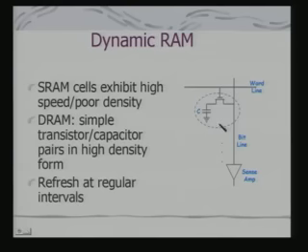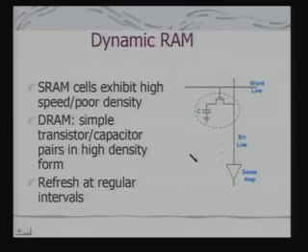But the only problem is that I need to refresh it at regular intervals. Why do I need to refresh it? If I am storing charge in the capacitance, the charge will leak out. So, I need to refresh the charge on this capacitance at regular intervals. It is not that once written, it is forgotten forever. Just like SRAM, where as long as the power is on the data is retained, this is not true for dynamic RAM, because charge can get leaked out. So, it needs to be refreshed at regular intervals.